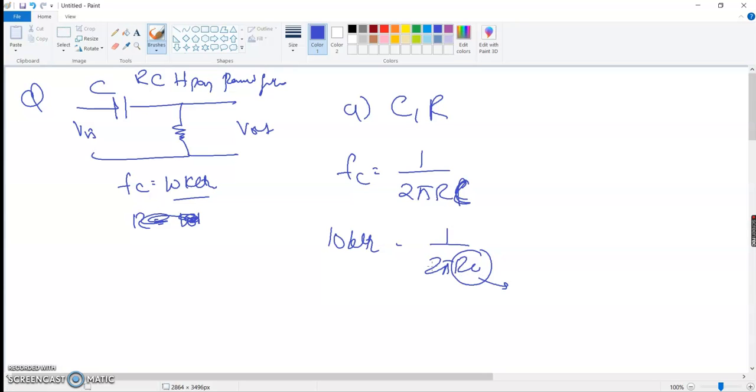But for resistors, we can make combinations of series and parallel and achieve something. Probably in the lab, we would have limited capacitors, right? So I'm going to pick a capacitor value of, let's say, 0.1 microfarads. So if I pick 0.1 microfarad, the value for resistance that I'm getting now is, give me a second.